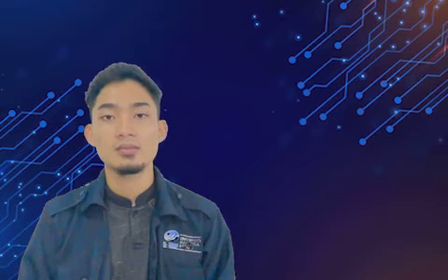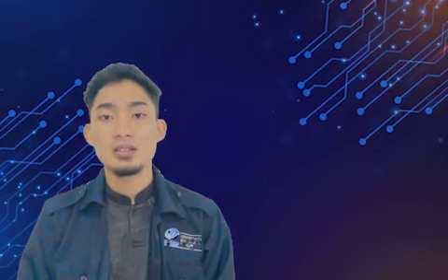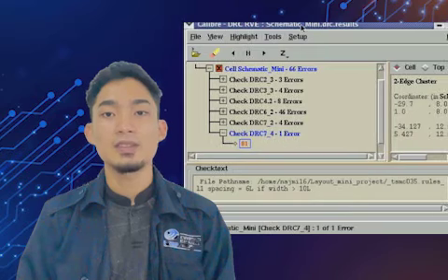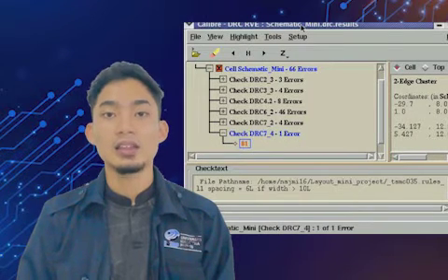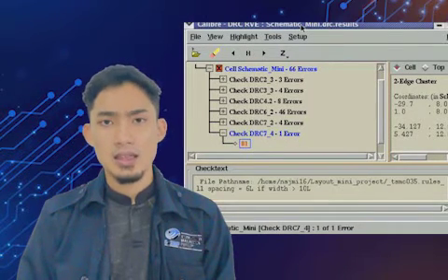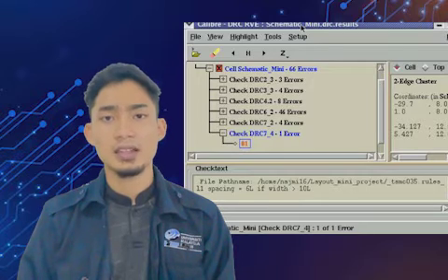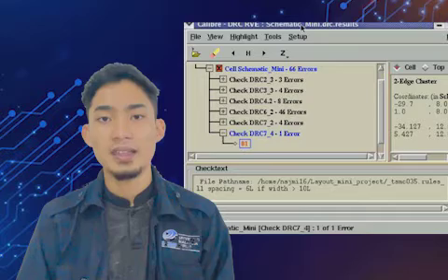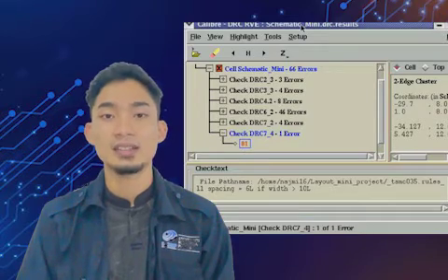Another error is metal to metal, which needs to be at least 4 lambda, and for ground and VDD, metal needs to be at least 6 lambda between metal to metal, because the size of the metal is larger than 10.